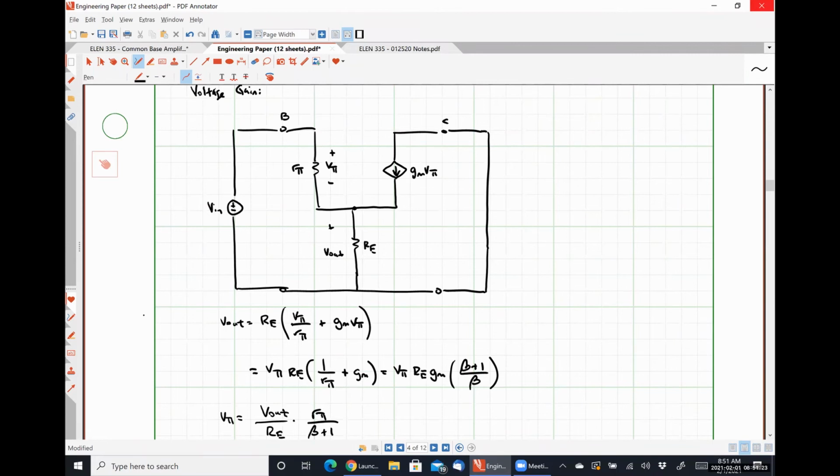Really, inherently, that's what it's doing. It's a fancy voltage divider with very high input impedance and very low output impedance, which we would consider a buffer, okay? So it plays the role in BJT amplifier circuits that a buffer amplifier plays in op-amp circuits, where a buffer amplifier is a non-inverting amplifier with a gain very close to 1, so that the output almost exactly follows the input.